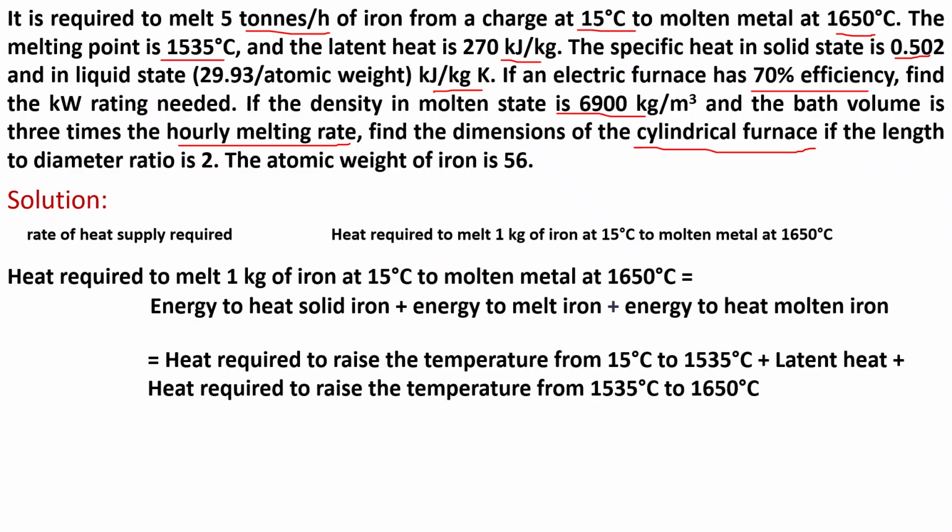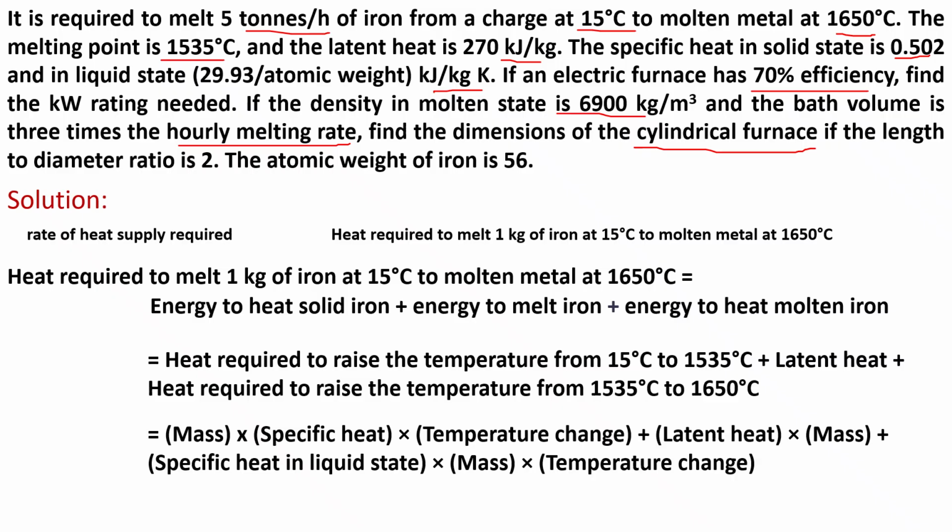First we look at the energy required to heat the solid iron. That is the heat required to raise the temperature from the charge temperature of 15 degrees Celsius to the melting point, 1535 degrees Celsius, plus latent heat, plus the heat required to raise the temperature from 1535 degrees Celsius to 1650 degrees Celsius.